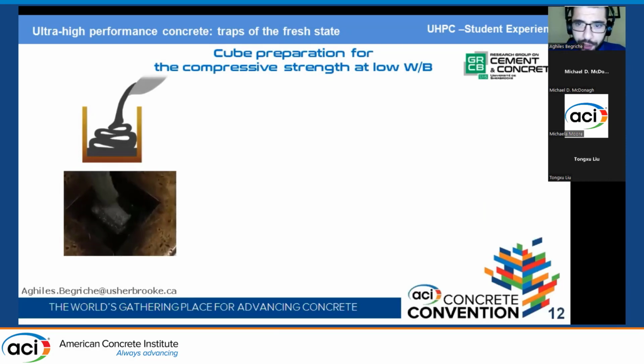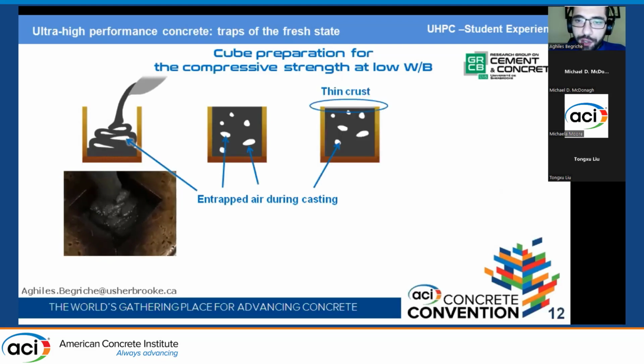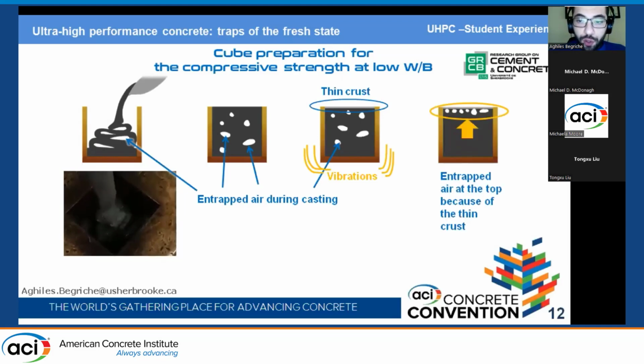And regarding the high viscosity of this kind of materials, in addition to the quick formation of a very thin crust on the surface of the sample, certainly due to the low water content and its evaporation at the contact of the atmosphere, after application of vibration, as we usually do, the entrapped air bubbles go up and stay entrapped under the surface.